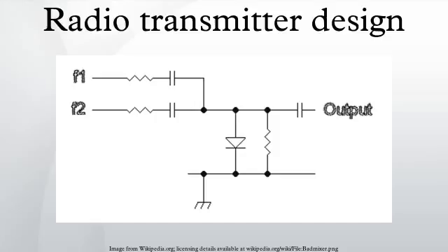Morse code is usually sent using on-off keying of an unmodulated carrier. No special modulator is required. This interrupted carrier may be analyzed as an AM modulated carrier. On-off keying produces sidebands, as expected, but they are referred to as key clicks. Shaping circuits are used to turn the transmitter on and off smoothly instead of instantly in order to limit the bandwidth of these sidebands and reduce interference to adjacent channels.